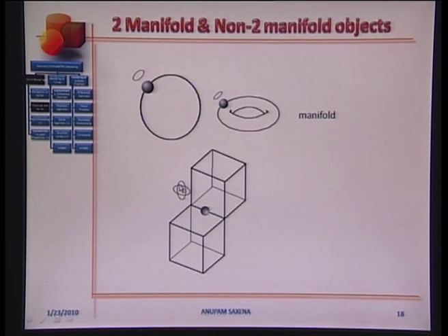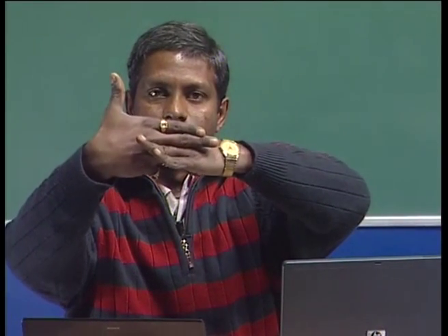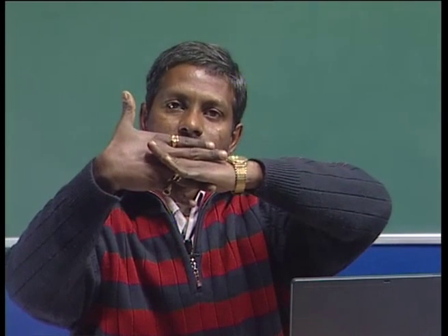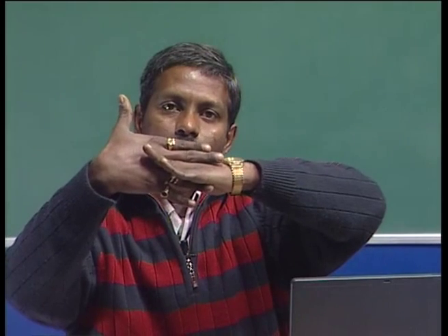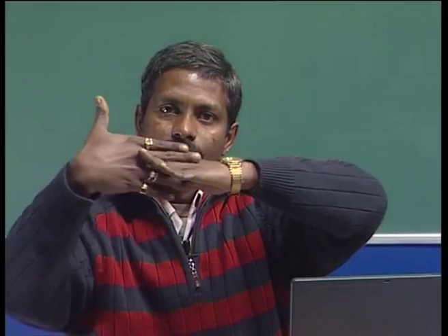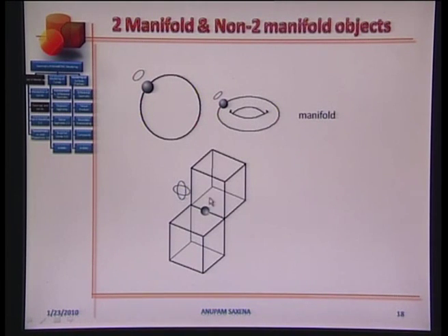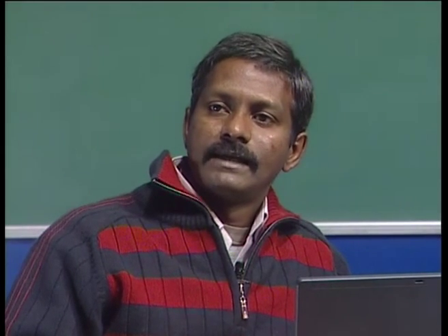So this vertical disk here is the result of the intersection between the ball and this vertical plane, and the horizontal disk here is the result of intersection of the ball and this horizontal plane. So the two disks are intertwined like how my hand looks. I cannot separate the two disks unless I tear one of them off. So here, the solid is a non-two-manifold, or in short, a non-manifold solid. Of course, if you recall the homogeneous three-dimensionality property of valid solids, this solid here defies that property.